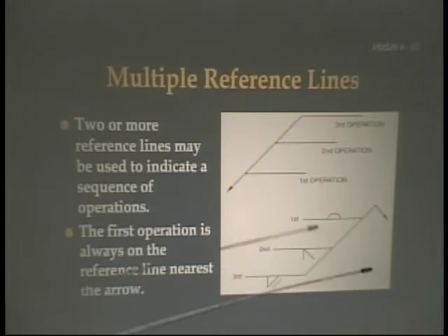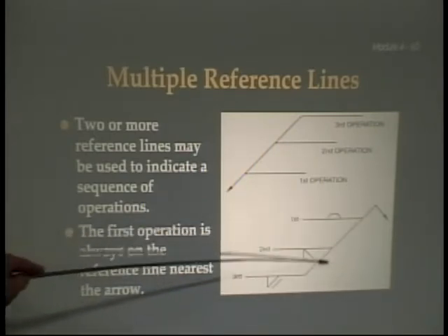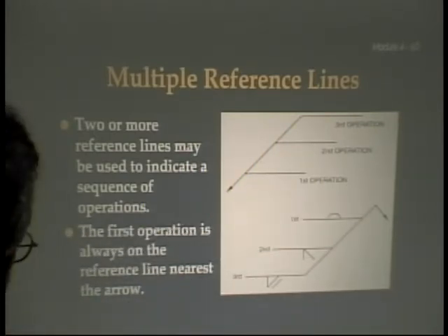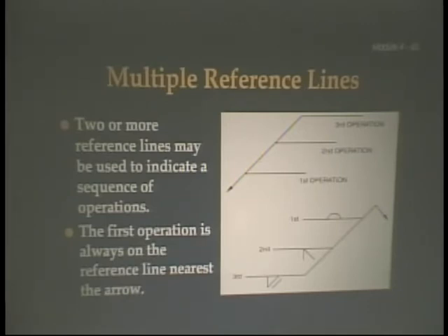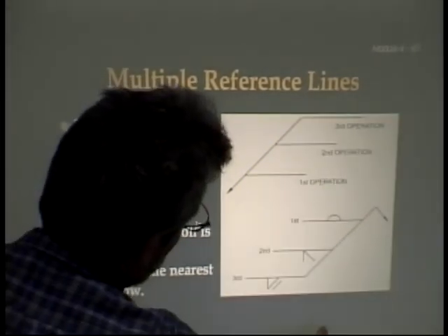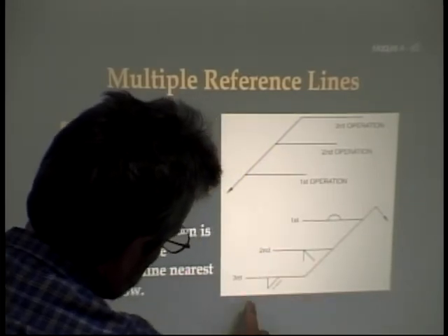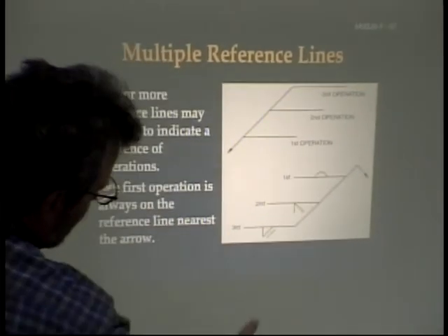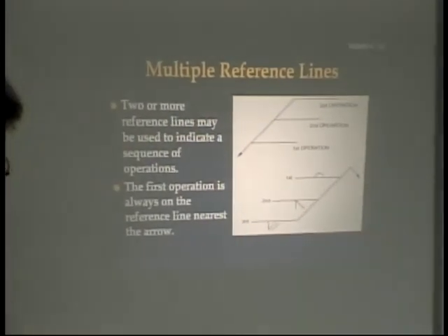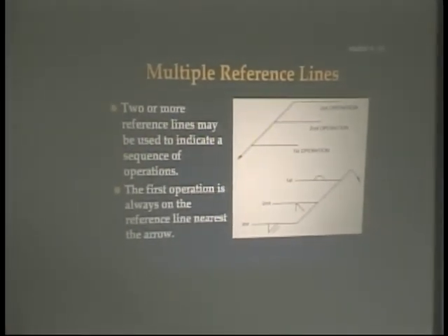So here we have, let me draw this on the board real quick, and I'll do it right here where you can see the symbol at the same time. So we have a symbol for a back weld, a symbol for a single bevel, and then a fillet weld with a flat finish. Can you see that pretty good?